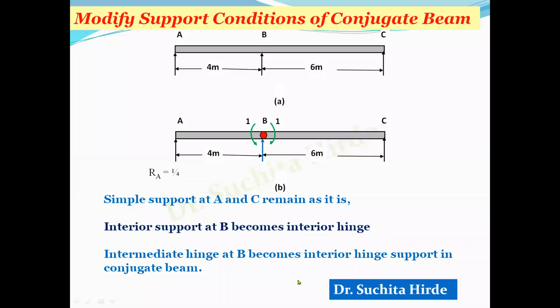In this case, we have to modify the support conditions. So simple support at A and simple support at C remain as they are. Interior support at B becomes an interior hinge. Then the interior hinge at B becomes an interior support in the conjugate beam.